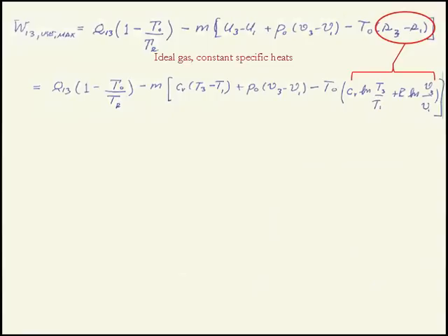There's another equation you can use. This one's the most convenient in this case because I already have all the numbers to go into that. Be careful about absolute temperatures once more. That must be an absolute, the temperature of the surroundings. And so must that guy. Okay, so that ratio of temperatures in this equation to find specific entropy, those temperatures must also be absolute.